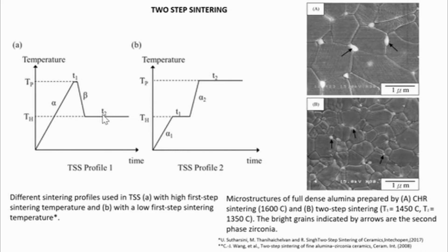By this method, the grain boundary diffusion is maintained, but the grain boundary migration could be frozen under pressureless sintering conditions. Therefore, the grain growth at the final sintering stage is suppressed successfully, and they showed this effect for yttrium oxide ceramics, and it's possible to obtain materials with nano-sized grains.